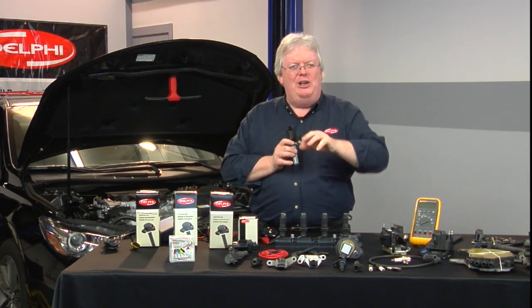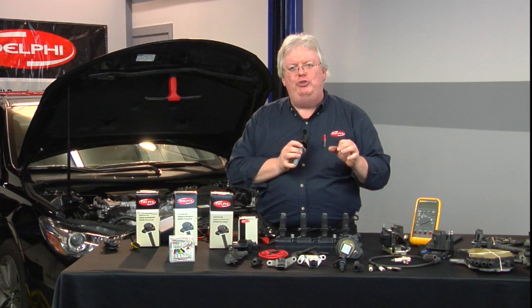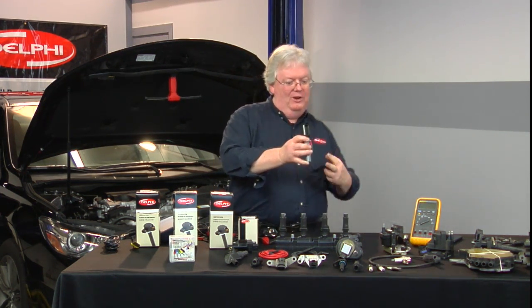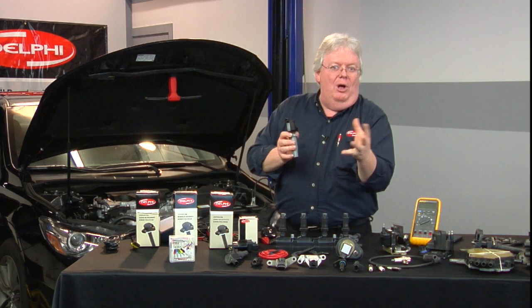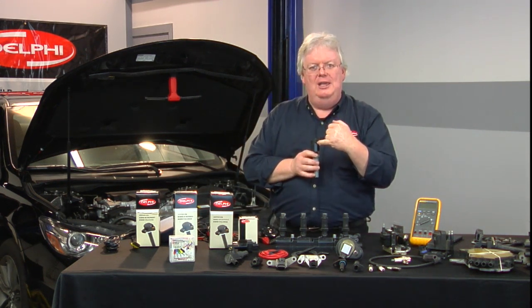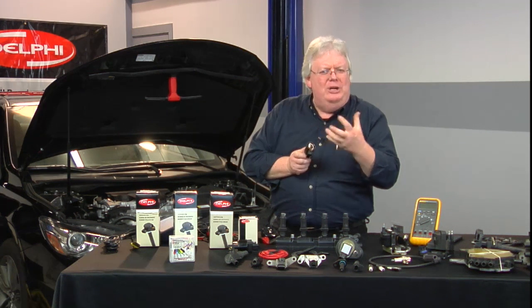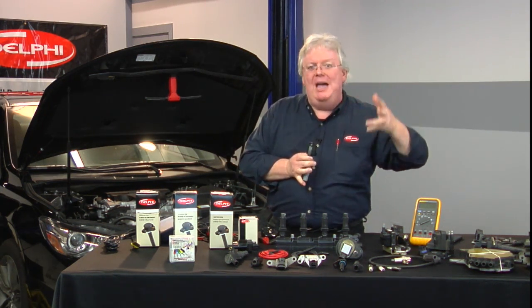Now, A is kind of close because if you thought of the coil driver trigger circuit as in the PCM, and that wire going forward to here, that would also work as well because it's the same circuit. But this truly doesn't have a trigger driver circuit built into it, so that really is what was in my mind when I wrote that question.